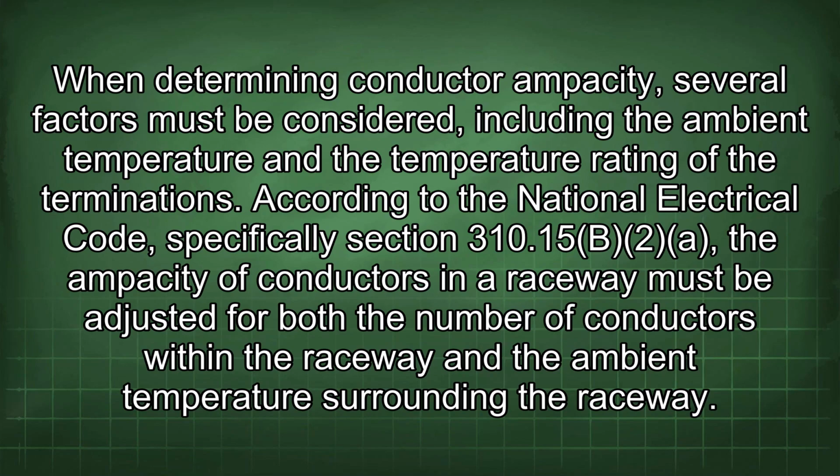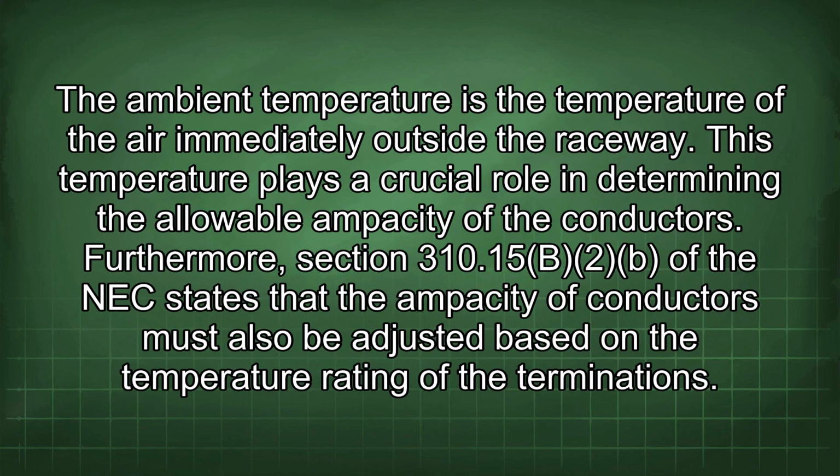When determining conductor ampacity, several factors must be considered, including the ambient temperature and the temperature rating of the terminations. According to the National Electrical Code, specifically Section 310.15(B)(2), the ampacity of conductors in a raceway must be adjusted for both the number of conductors within the raceway and the ambient temperature surrounding the raceway. The ambient temperature is the temperature of the air immediately outside the raceway. This temperature plays a crucial role in determining the allowable ampacity of the conductors.